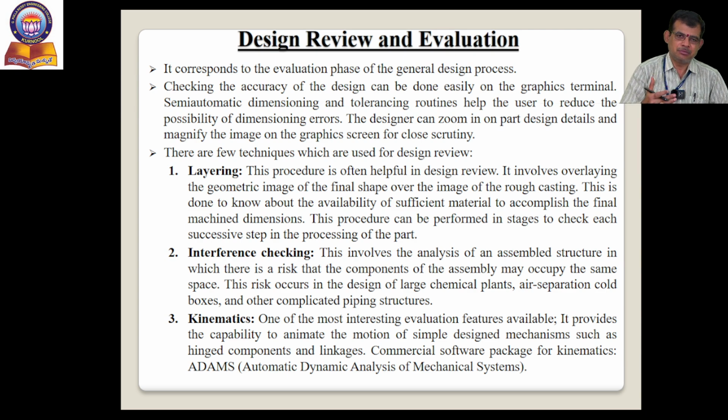So any object when you are creating, you should create it with a slight tolerance on the upper limit, so that at the next stage, the surface finish stage, when you do the finishing activity, the exact dimension will come to you. At the basic level, if you prepare it at the exact level, when you go for surface finishing activity, an under-dimensioned component will result. So you must keep this in mind also. This procedure can be performed in stages to check each successive step in the processing of the part. At every stage you can do this layering.